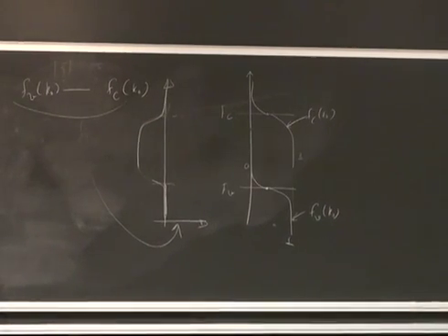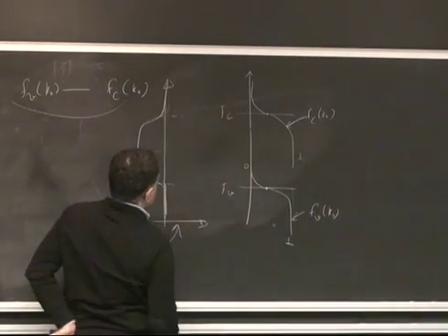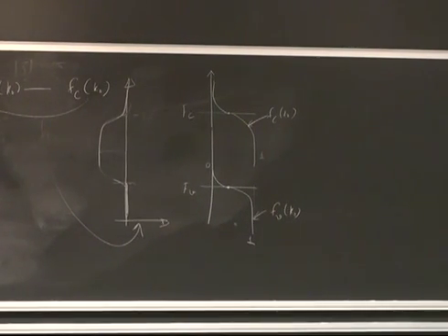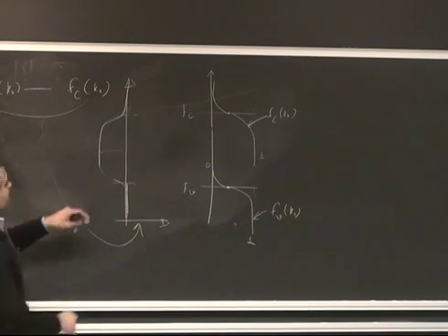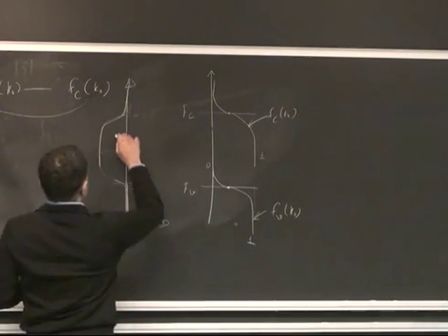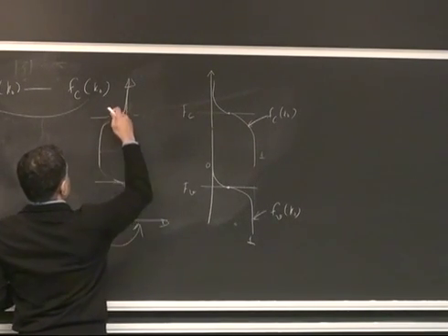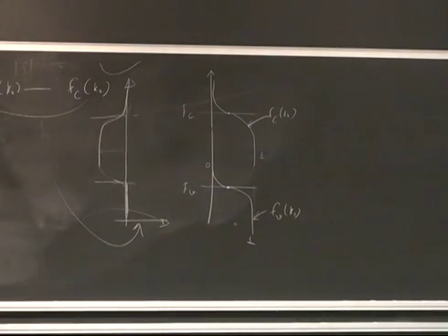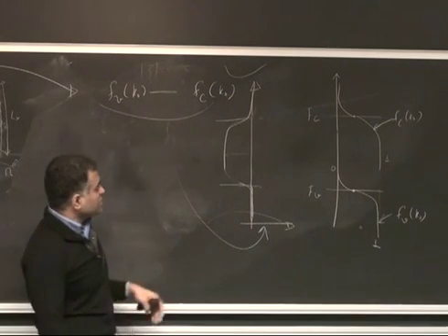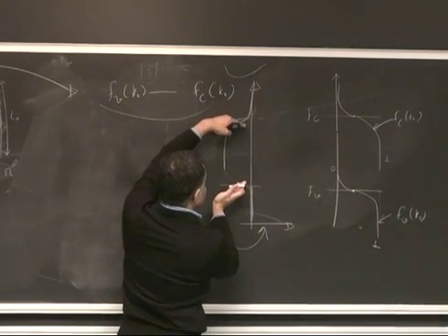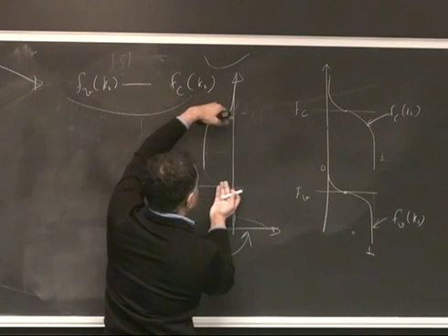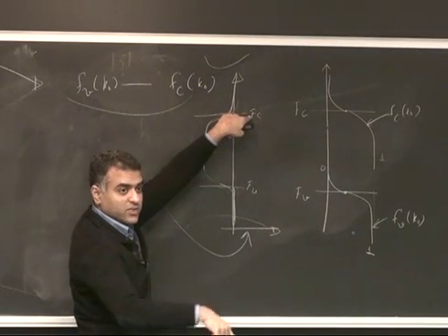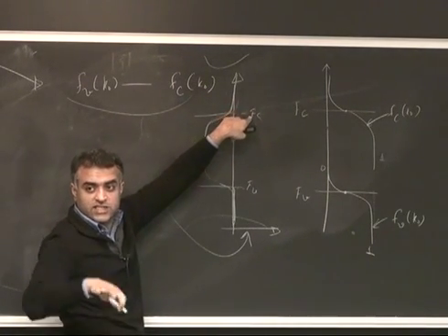Okay. So what you see is it'll be 1 somewhere in the middle of the gap. But what is interesting about this point is this window. It's extremely critical. If your band gap is like that, it does nothing for you. The band gap of the semiconductor is useless, right? Nothing much happens. So the band gap of the semiconductor must be smaller than this window, and the Fc must be inside the conduction band, and Fv must be inside the valence band. Otherwise, you are not doing anything very useful. So that's a very important thing.